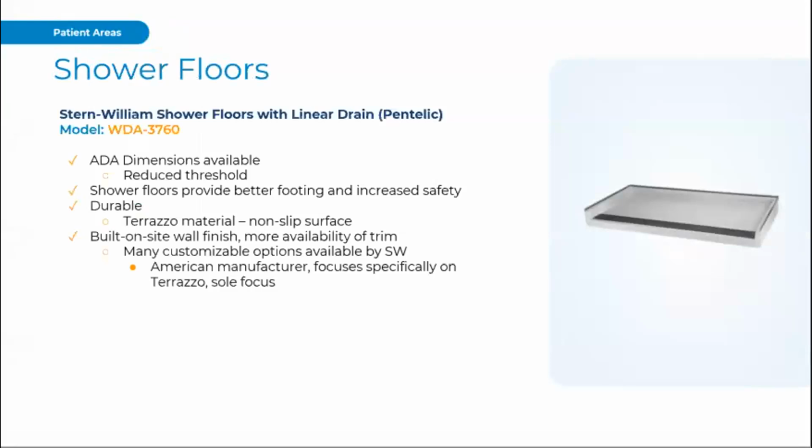So there will most likely be an assisted bathing area on site, as well as everything from personal showers to therapeutic tubs. So starting with their shower area, we have seen a trend towards a more stylish finish. Using these shower floors with a linear drain provides a little bit of a nicer aesthetic, as well as meeting our code aspects of having the drain area. More importantly, in my opinion, is that terrazzo is a durable and naturally non-slip surface. Slips and falls while bathing can be demeaning to the user as well as physically damaging. These floors are important in preventing that.